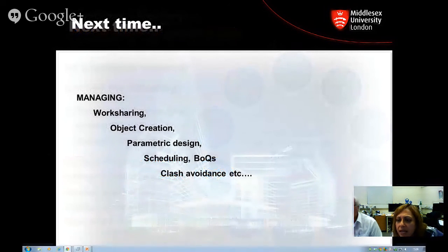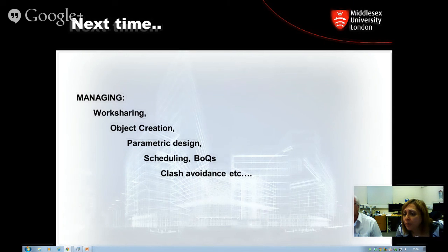Sorry. What is the LOD required in the design stage? It depends what design you're talking about, Mohammed. So the architectural might be at level 200, maybe 300. The structural is usually higher, maybe 300, 350. The design stage of the fabricators or the manufacturers would probably be at 400, 500, and same thing for the design of the shop drawings of the contractor, again 400 or more.